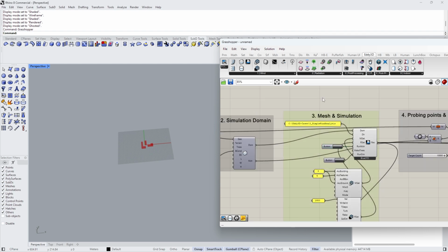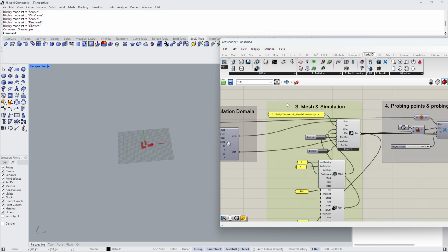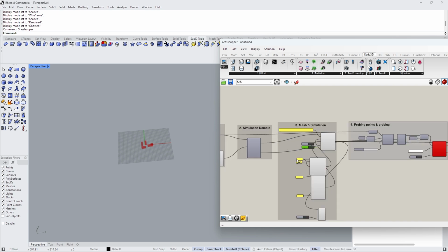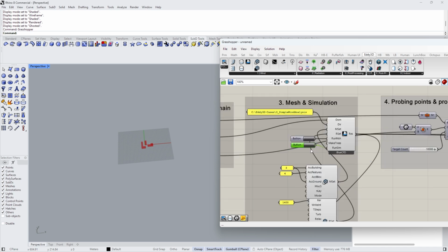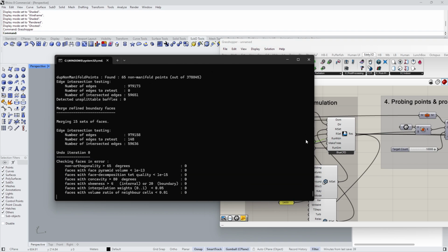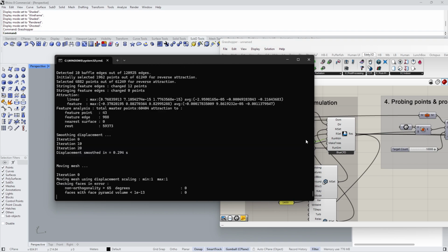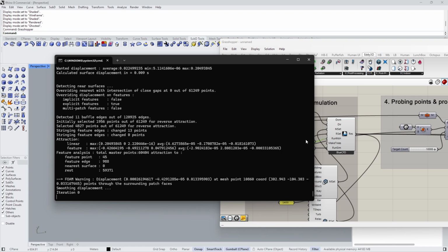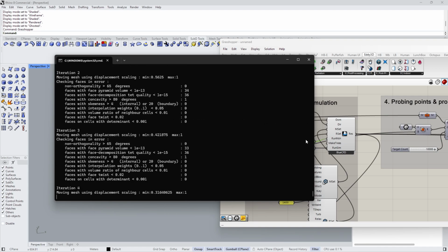What's great here is that a lot of the simulation is already happening in here, and we don't need to worry too much about writing and running too many different things before we can actually do the simulation. Here's just two buttons, which is really great. So they streamlined the whole process quite a lot. The only thing is that you lose a bit of track of what's possible, because again, it's an interface for OpenFOAM. Now anyway, let's run this. Creating the mesh first. I assume this is equivalent to the block mesh and snappy hex mesh in Butterfly.